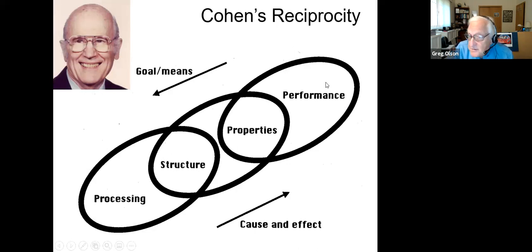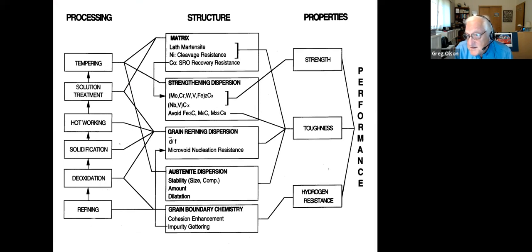So we've used that as the backbone of a system structure of materials, adding to it Smith's structural hierarchy, so that each design project starts with this kind of system chart, where a performance goal of the material can be mapped to a quantitative set of property objectives, which can relate back to subsystems of hierarchical material structure, which dynamically evolve throughout the sequential stages of processing. And this allows us to identify and prioritize the structure-property and process-structure links for which we want to build predictive design models. And at this point, we could use empirical interpolative correlations, but in fact, given the power of the fundamental CALPHAD databases, our commitment from the start was to use mechanistic models, parameterized to use the fundamental data in CALPHAD, to be far more predictive than is possible with empirical modeling.